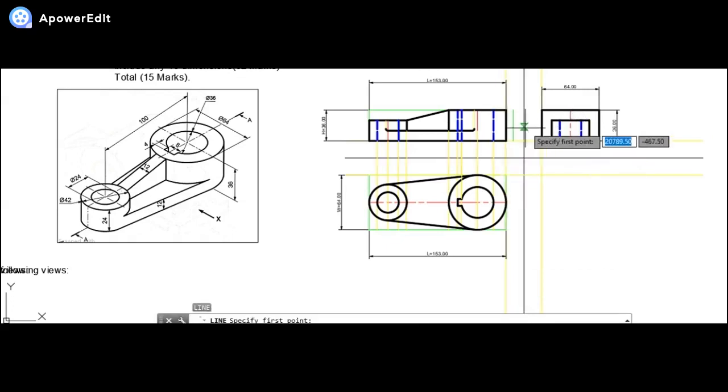Now for our knowledge's sake, let us draw the projection lines one by one. Let us get all the projection lines from here. We have already drawn the first one, this was the second one. All the horizontal projections for the side view, we are getting those very specifically. Even in the front view and top view, what we missed out was the rib. So just that rib we will be completing.